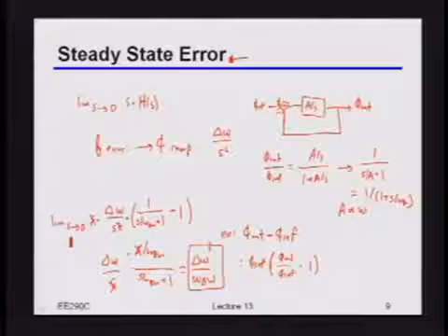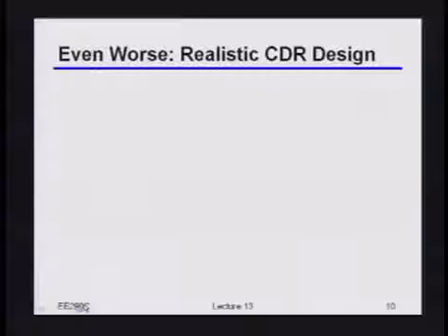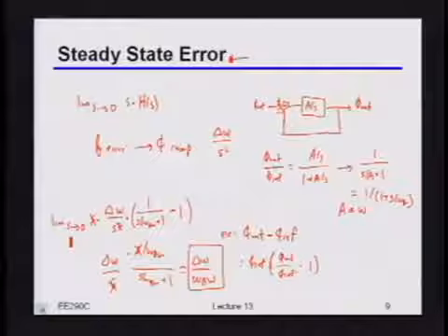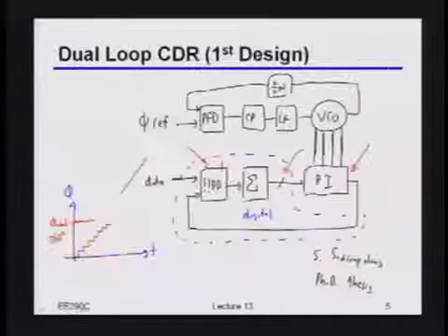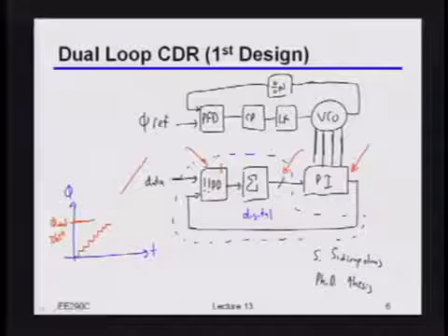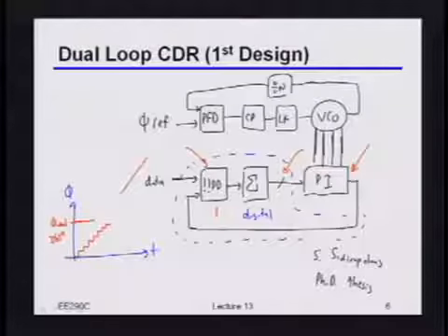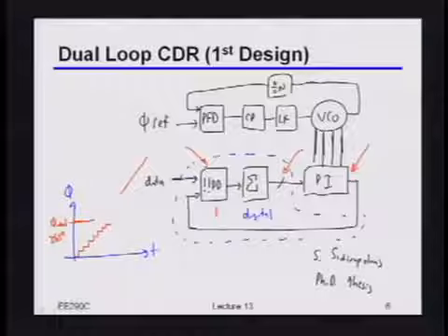Okay? So, now the question is, just one thing that is going to make life actually a little bit worse, which is that, as I was mentioning before, those updates are coming at a pretty high rate. So if I'm running this thing at, let's say, 12 gigahertz or 12 gigabits or whatever it is, I'm going to be getting these updates at a 12 gigahertz rate, or 12 gigasample per second rate. And that's probably much, much faster than I really want. That's probably much more data than I can really effectively use, or at least building the digital processing to run at that speed will probably cost me quite a bit of power.